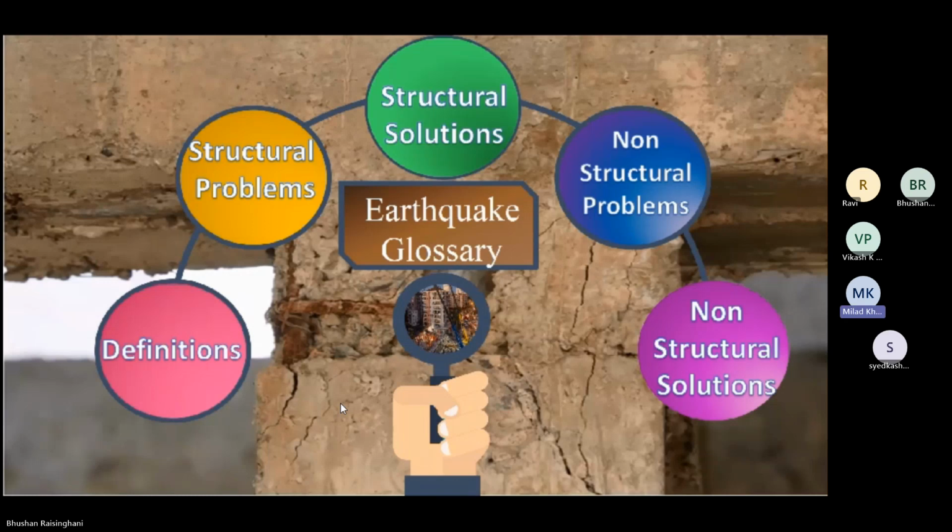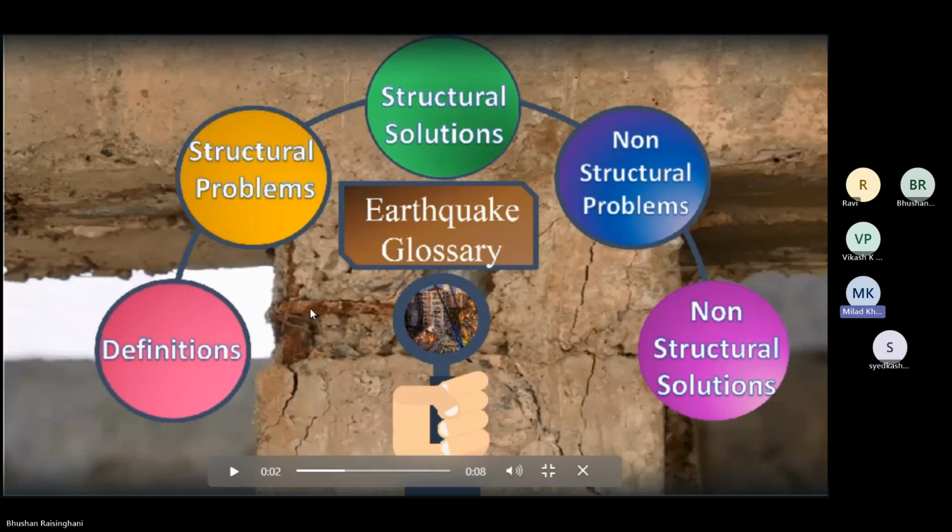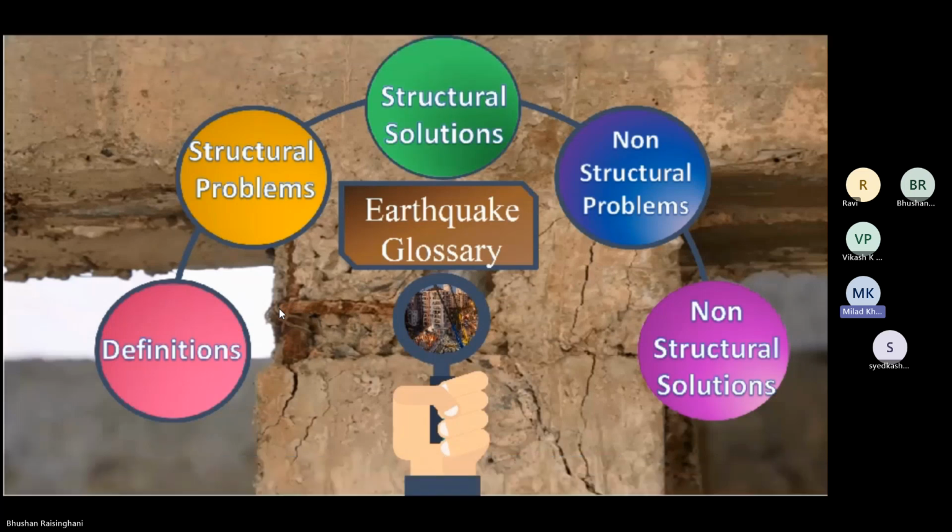You can see the stirrups in the slide, how they have small concrete cover and cracks. So when we have small concrete cover, we should think about the corrosion that will happen to these stirrups. Please, the next one.